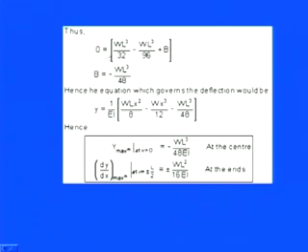So by putting x equals L by 2, y equals 0, in the deflection equation, we have 0 equals wl cube by 32, because here we simply put x equals L by 2. So x is totally replaced by L by 2, and we have wl cube by 32 minus wl cube by 96 plus the b coefficient, because we want to calculate this b, so we have minus wl cube by 48. So now we have the a value and the b value: a which is 0, and b which is minus wl cube by 48.